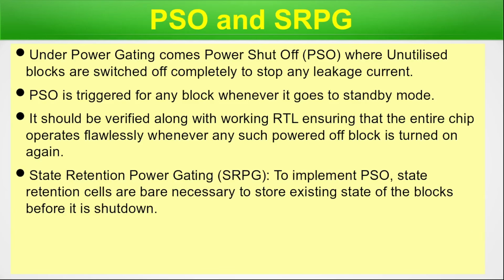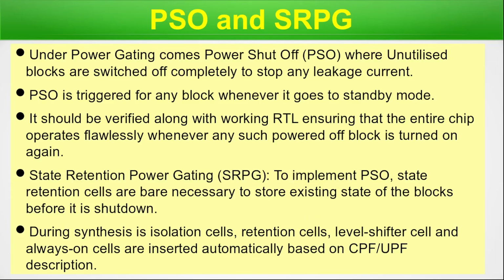State retention power gating, SRPG. To implement PSO, state retention cells are a bare necessity to store the existing state of the blocks before they shut down. During synthesis, isolation cells, retention cells, level shifter cells and always on cells are inserted automatically based on the CPF or UPF description. So we are done with the power shutoff, that is PSO, and state retention power gating, that is SRPG, in this slide. Let's move on to the next slide.